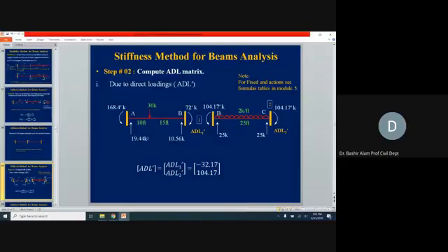These vertical reactions you need to find out. You have the unbalanced moment now. If the unbalanced moment was not there, you can split the load between A and B. On A, it will become 30 times 15 divided by 25. On B, it will become 30 times 10 divided by 25. This is for the simply supported case, but now we have fixed ends and we have the unbalanced moment. So how much is it coming to?